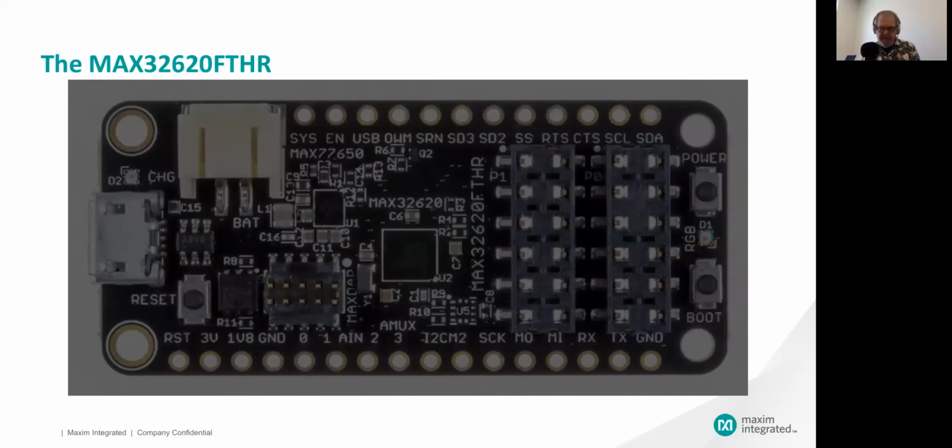Next, we have 2 indicators. Both of the indicators are 3-color LEDs. They're rather different in capabilities. On the right there's a LED marked D1. It's connected to GPIO pins, 1 for red, 1 for blue, 1 for green. And that means you can directly create 7 colors. Now, don't get too excited, but 7 is the number. You can do pulse width modulation if you want to create other colors, but with direct control, it's going to be 7.